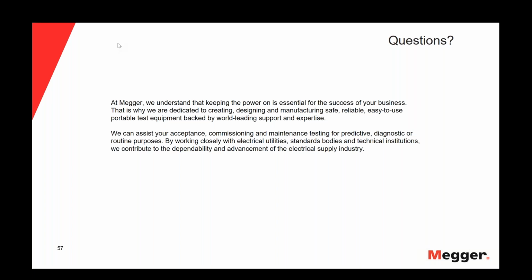We're talking PD. So if you talk to, let's say, Europeans, Middle Eastern, all of these areas, the monitored withstand is the VLF test. You have to do it. It's the over voltage test, plus monitoring the PD during commissioning. So that is very common, and it's now the latest, hottest trend. And the standards committees are now slowly getting in motion. They need a little bit of time to gain inertia. You know how this is. And now it starts to become evident that more and more amendments at first are made before the big revisions of the standards are published to allow for this monitored withstand. So VLF at 3U0 or some other test value at reduced testing time if you do PD.